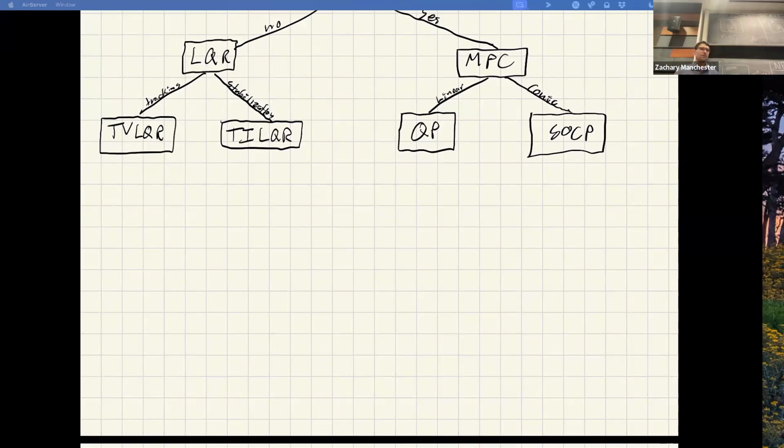And then with the domain randomization stuff in RL, you're basically taking your model and putting noise all over it and trying to optimize a single feedback policy that'll work over any of those samples of random model perturbation. So it's a sort of sample-based randomized version of the robust control ideas, right? There are a lot of related ideas, but domain randomization is really a robust control thing, I would say.